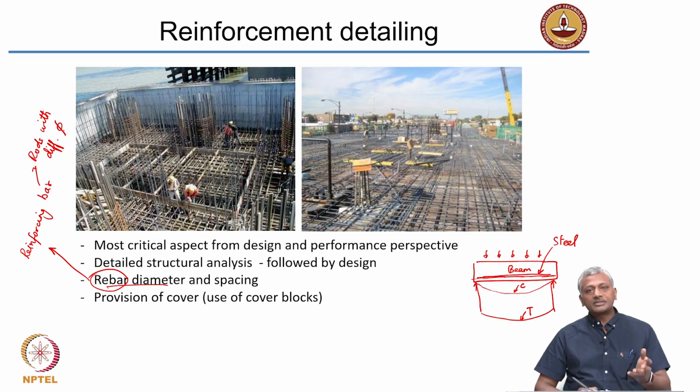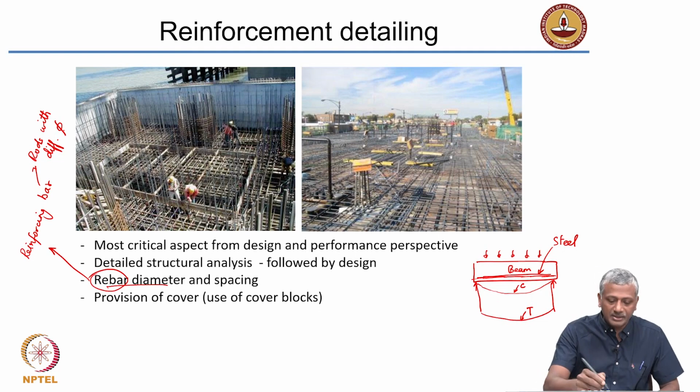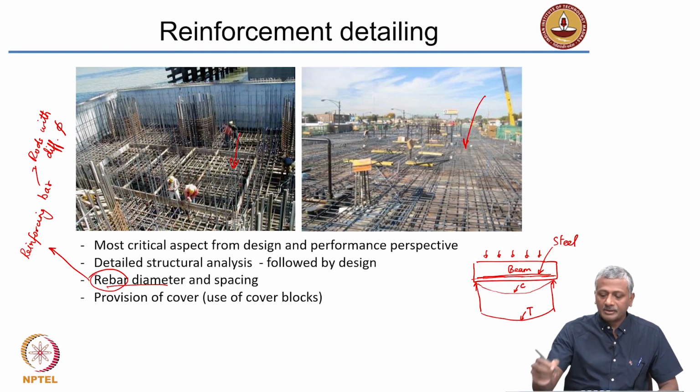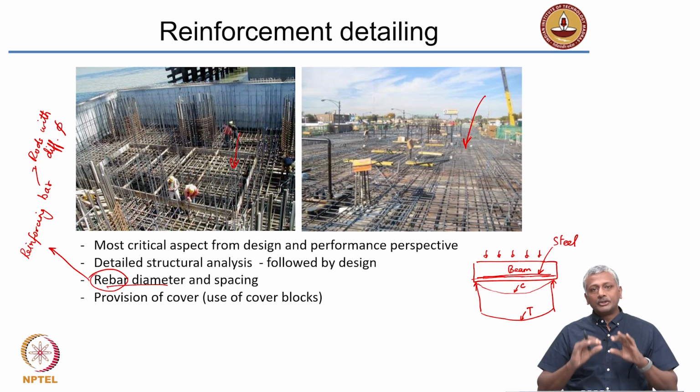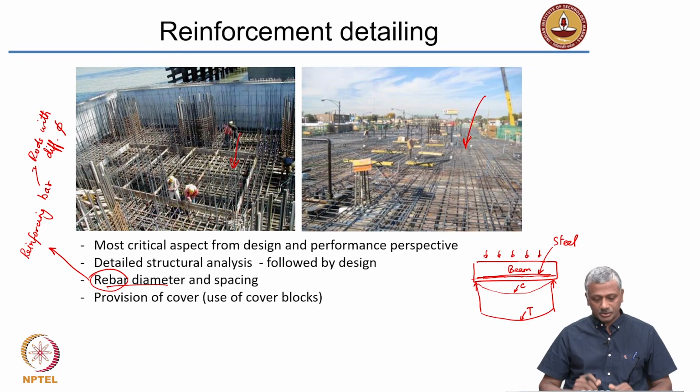Okay. So all this of course you will learn in more detail when you actually encounter courses on reinforced concrete design. But it's very important to understand that before the concrete placement into the formwork is done, the reinforcement has to be appropriately designed and laid out like you see in these pictures here. The reinforcement is properly laid out before the concrete is poured to ensure that you are getting reinforcement in all the zones which are going to be experiencing tension.